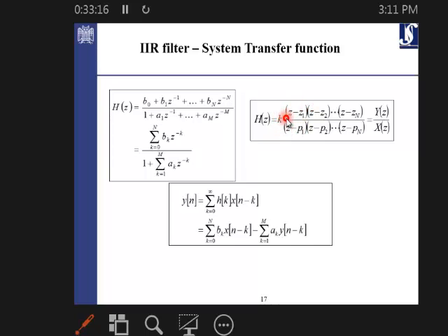And you have a constant gain, if the system has a gain. This kind of definition is the most complete definition of every system that you might have. It can also be represented like this. Just you take the first coefficient to be 1 as a constant, and then you normalize all the other coefficients with a_k. It's not a problem. Then you apply such a filter to the input signal to get the output signal.